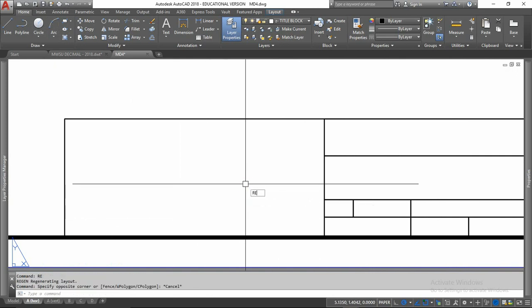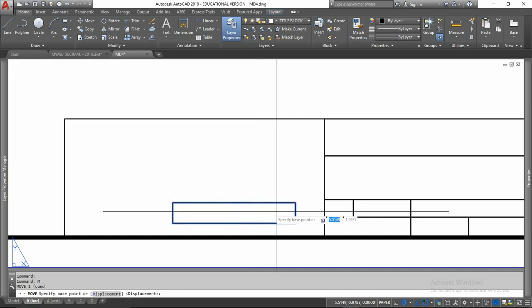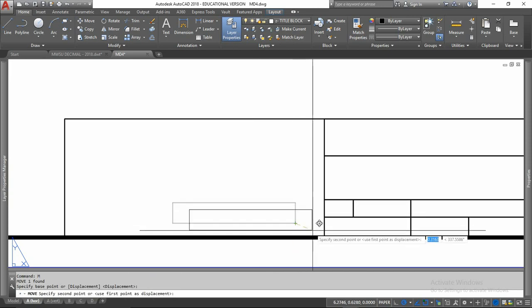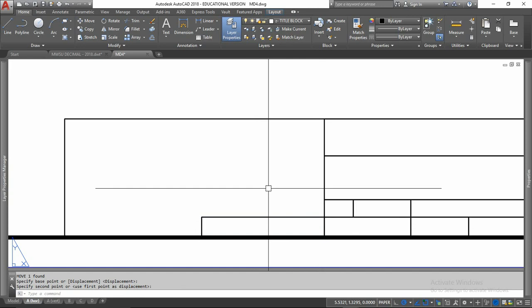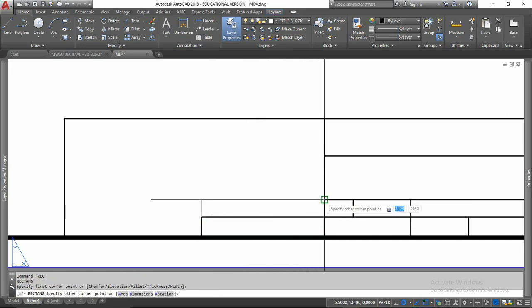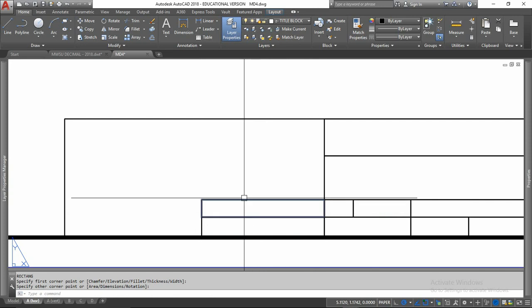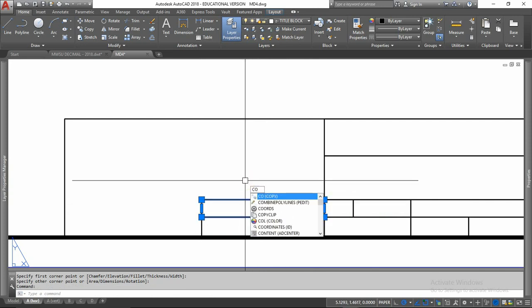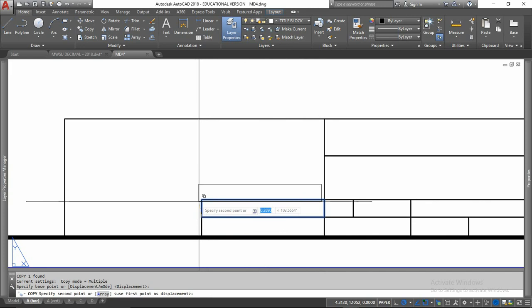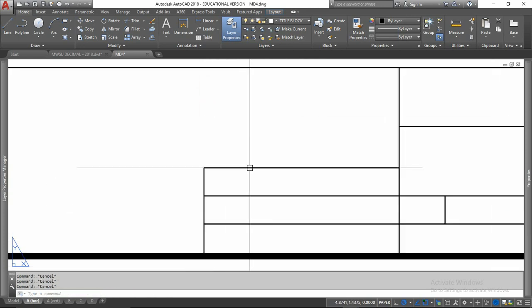Okay. Now I'll come over and I will do a rectangle of 2.125, 11/32, and I will move it there, and another rectangle here up to there, and I have another rectangle exactly that same size. I'll do a copy from this bottom to this top. Again, if that's what's going to be true and common, then use those object snaps.